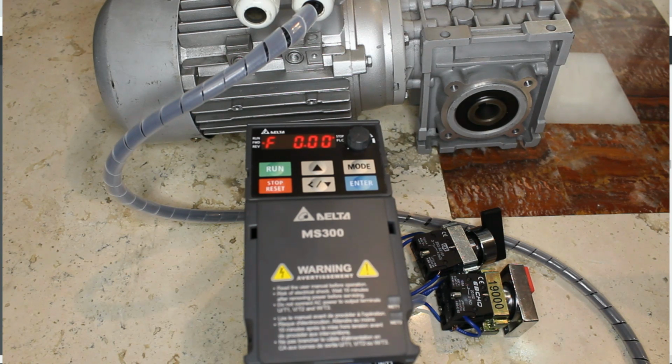Which one am I going to affect? So we can start compensating this. For example, if we need precision, we need to hit our position loop. If we need torque, then we need to hit our torque loop. And the other ones, since they're manual, we have to start using them. But this is the finer tuning part.